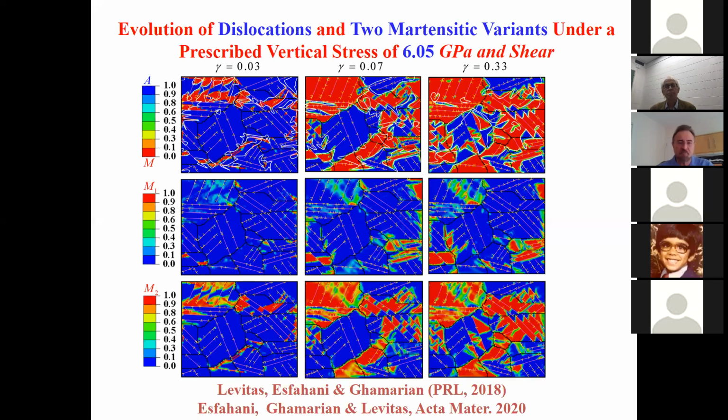But the bad point is that temperature usually reduces yield strength. And that means that non-hydrostatic stresses will be limited by lower yield strength. And also it may activate different mechanisms of stress relaxation, like diffusion, and then instead of getting our phase transformation, creep may reduce stress concentrator due to dislocation pileup. So that is why we did not study the effect of temperature, but